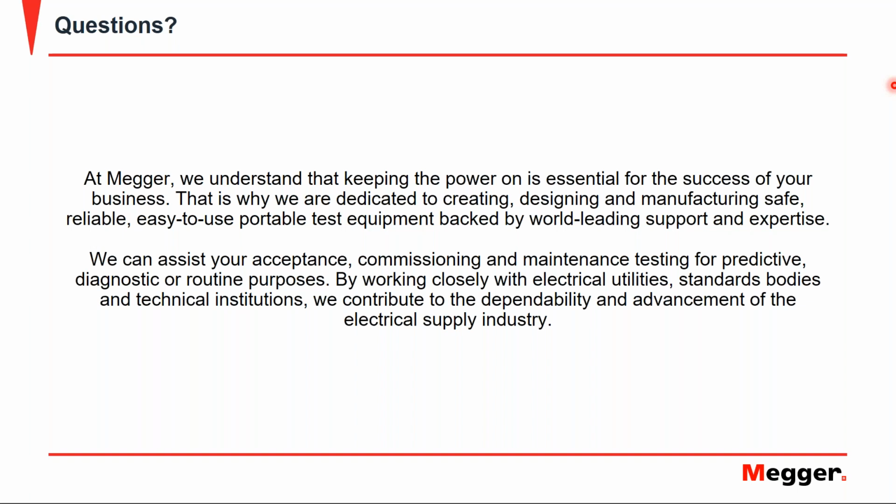Thank you, Hein. Charles, how high do you go for test voltage to determine a good cable? So what I did in this example is I followed the IEEE 400.4, which is basically a guide for doing damped AC testing on power cable rated 5 kV and above.